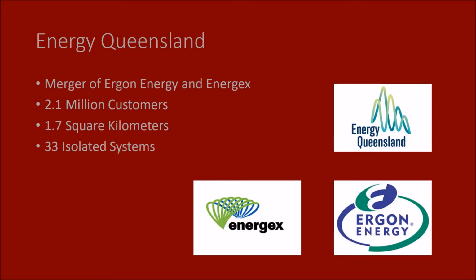PowerFactory is a relatively new load modelling software being introduced into the Ergon Energy side of Energy Queensland. One significant advantage of this software over many other existing softwares is the functionality to simulate non-symmetrical loads, whereas previously most softwares were limited to balanced load flows and fault studies.